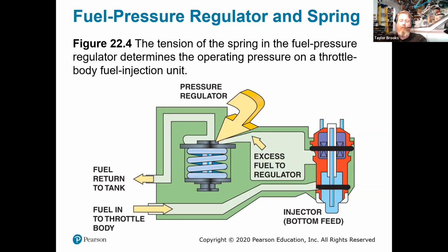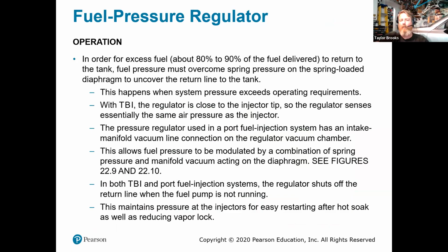The spring pressure will close the valve off, and then we will start the process all over again. Now, these systems will allow for fuel pressure to be maintained, and when we have this system vacuum controlled as well, where we're taking a sample of the manifold vacuum to allow for it to ramp up more fuel pressure when needed when we're under full throttle and there is less manifold pressure. That allows the engine to match the performance that is being expected by the driver.